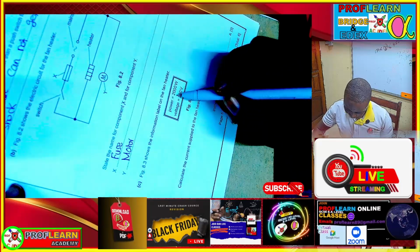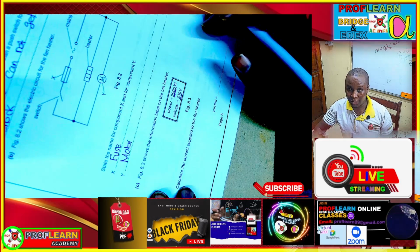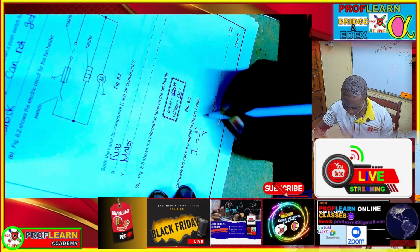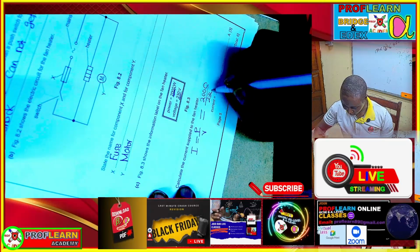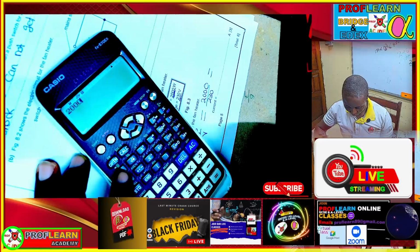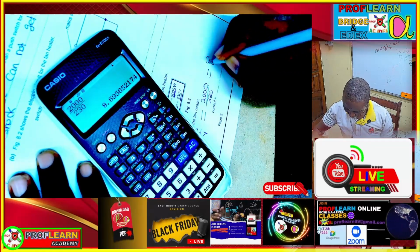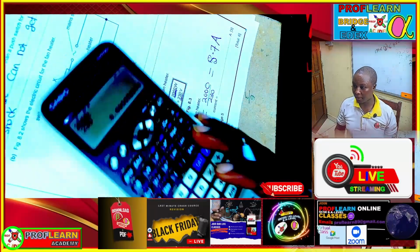Calculate the current. You can see the power is 2000 and the voltage supply on this device is 230. So current is equal to power over voltage, which is 2000 watts divided by 230. If you work it out, 2000 over 230 translates to 8.7 amperes as the answer for this particular case.